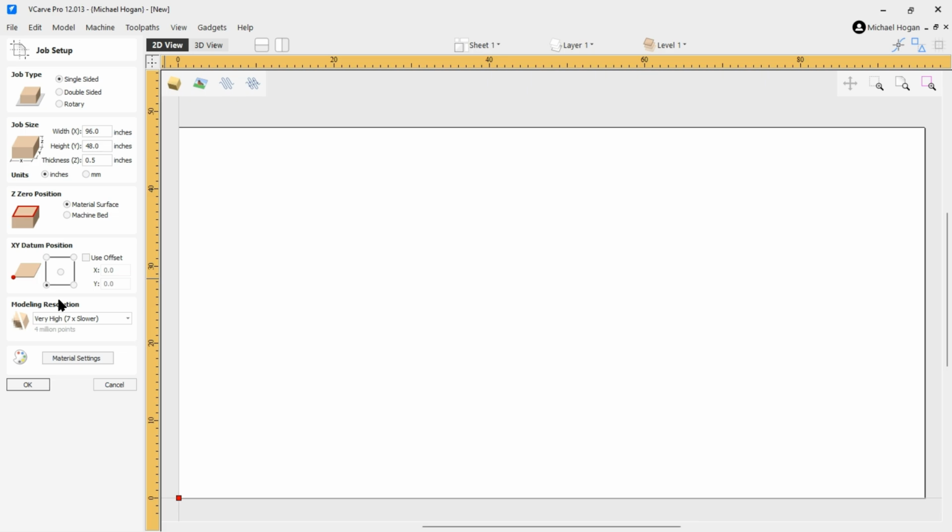It's important that you remember how these settings were set up for your DXF files, because your toolpaths have to be set up a certain way, and certain settings, especially these settings, when you go to the CNC machine. The same thing applies here when you're creating DXF files for importing.